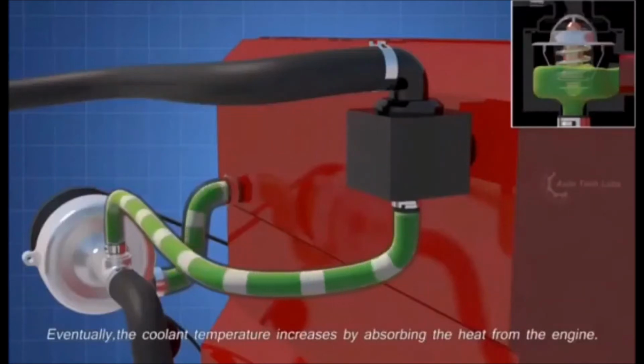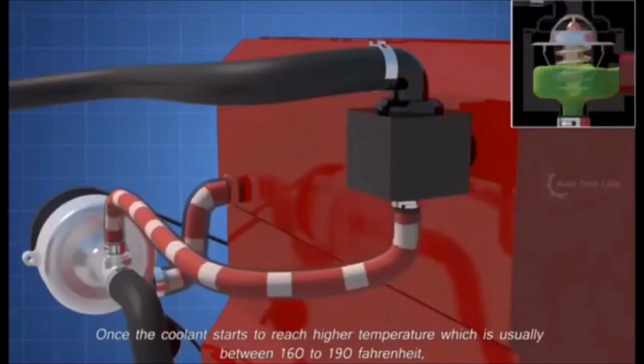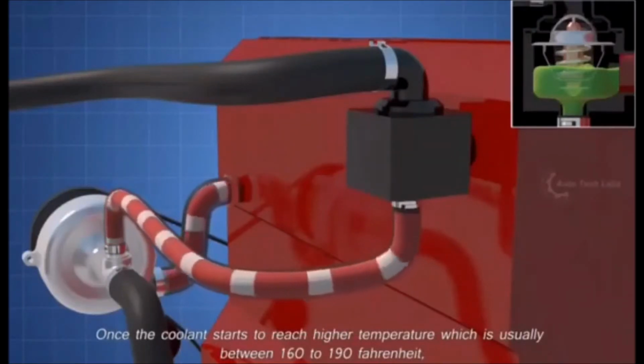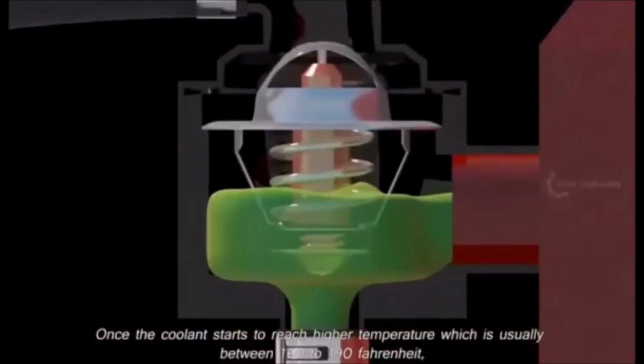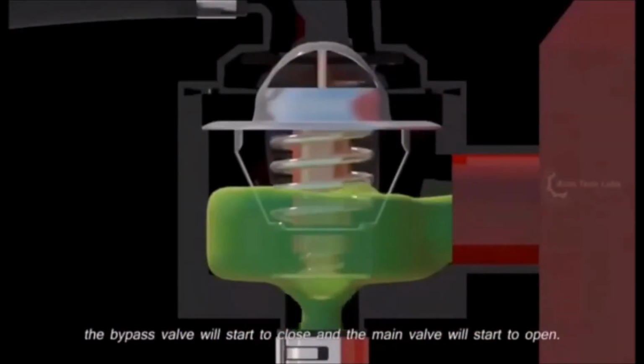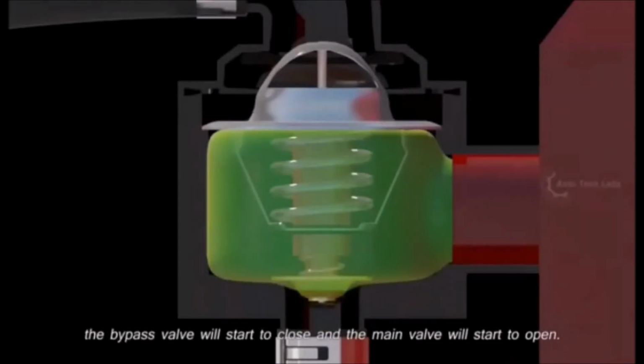Eventually, the coolant temperature increases by absorbing the heat from the engine. Once the coolant starts to reach higher temperature, which is usually between 160 to 190 Fahrenheit, the bypass valve will start to close, and the main valve will start to open.